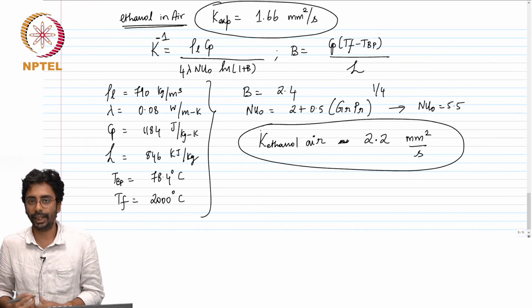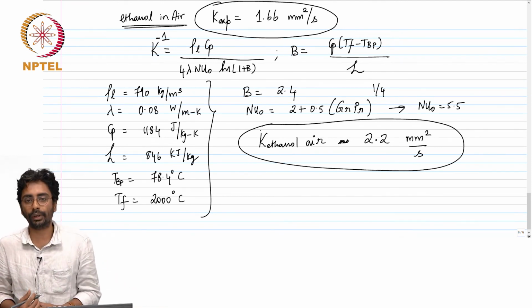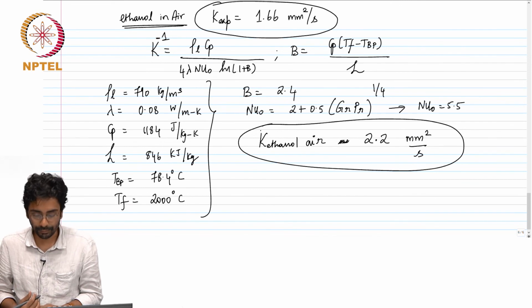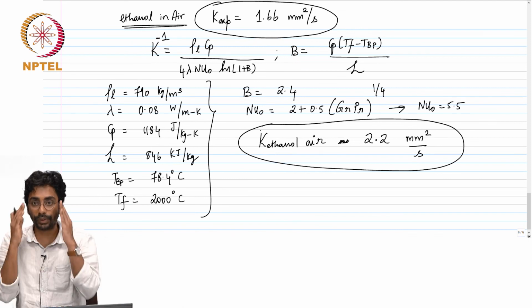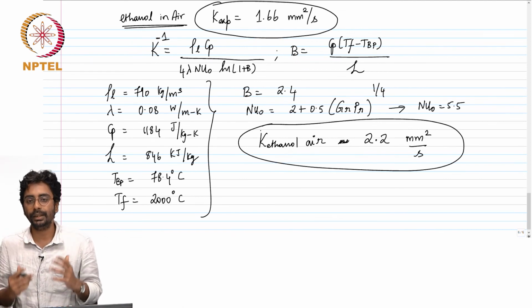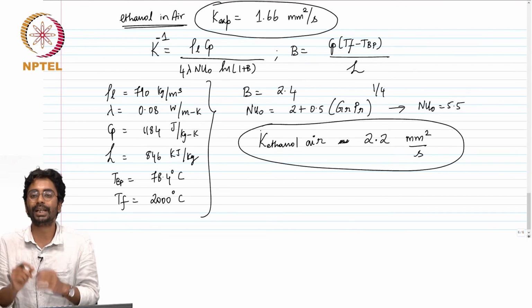Okay. I hope through this lecture you get a good appreciation for the process of droplet vaporization in a combustion chamber, and I also hope you will go back and check a combustion text to understand why Nu by Nu 0 is logarithm 1 plus b by b. The key words that you should use for the search are the phenomenon of blocking effect.